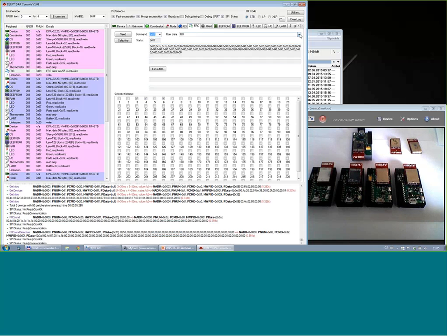And in order to show you it in practice, I will select here this command, which says, okay, peripheral number is LED green, so I will use the LED green, and the command is LED set on, so switch on the LED. And here, FFFF, this means for hardware profile ID. So we will use all the hardware profile IDs.